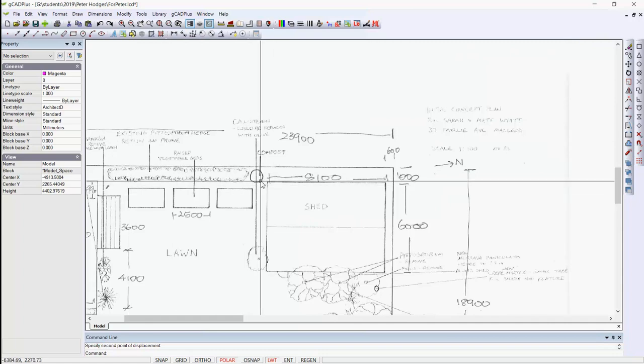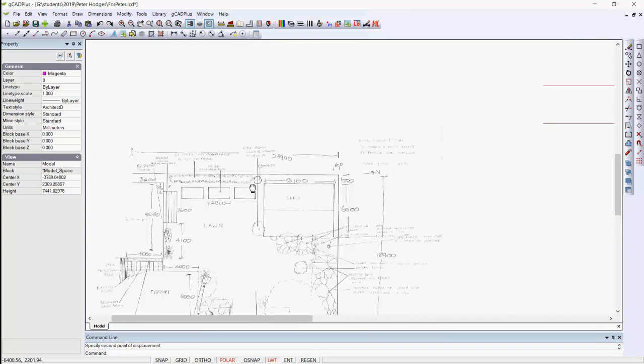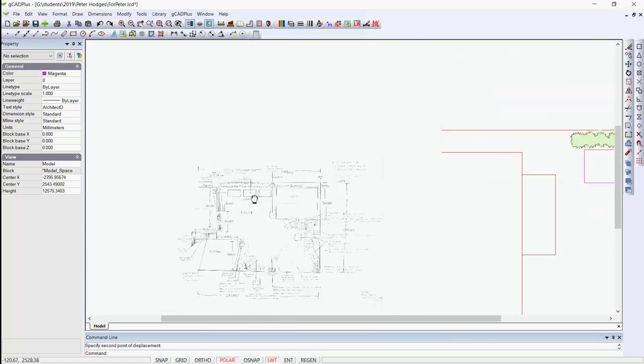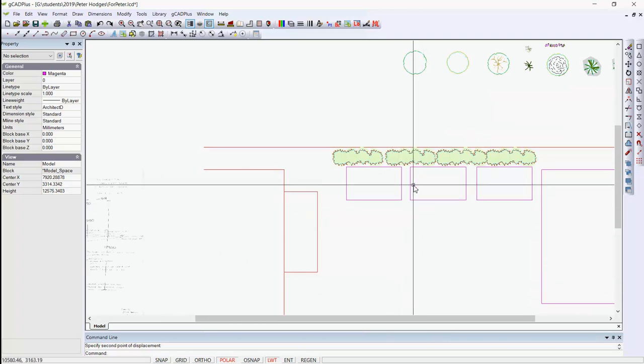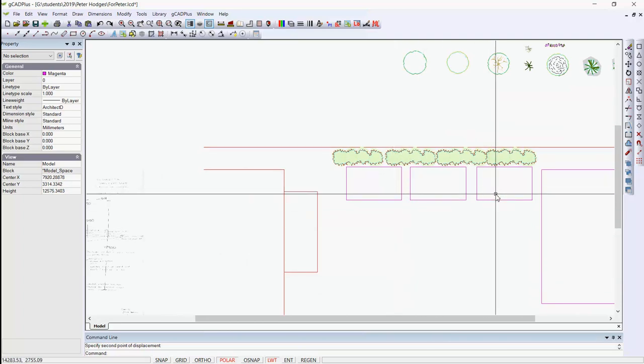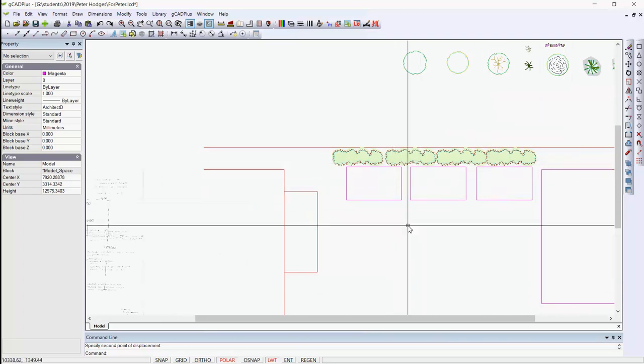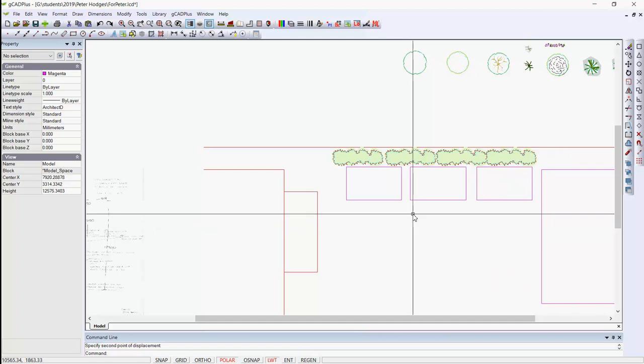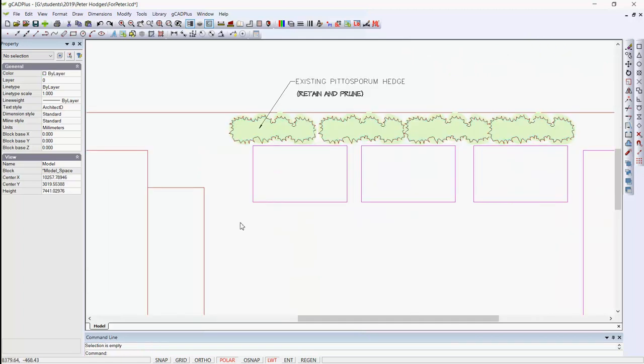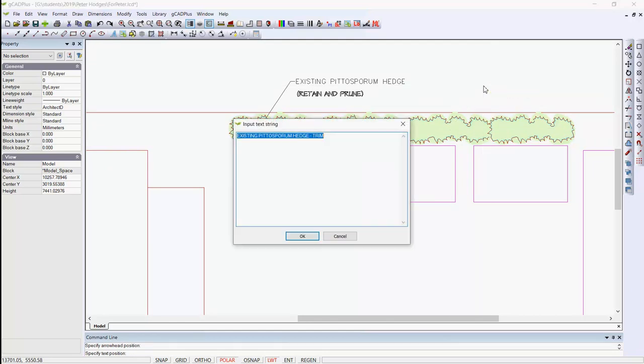A compost bin is going to go in place alongside the hedging. So this indicates the raised beds, or the vegetable beds, and some hedging there. So we're making progress. Well, there are a number of ways that notes can be added to a drawing. You can use a leader, dimension, leader, and just click and then move to a position.